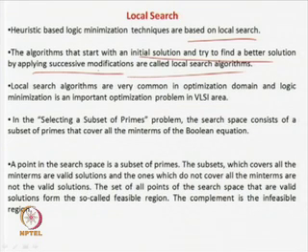Initial solution means the initial cover. In this case, you are given a sum of product form of a Boolean function. So, obviously, it will cover all the minterms. That is very well known. So, that is your initial solution, and you try to find a better solution by successive modifications. As we will see by examples, you try to modify some of the product terms, so that some of them can be done away with totally. If you find some redundant terms, they can be done away with.